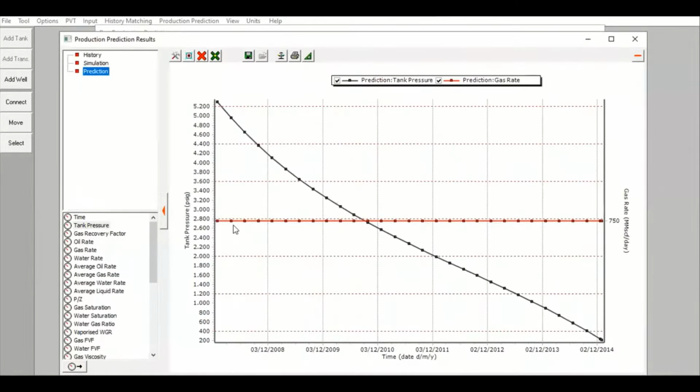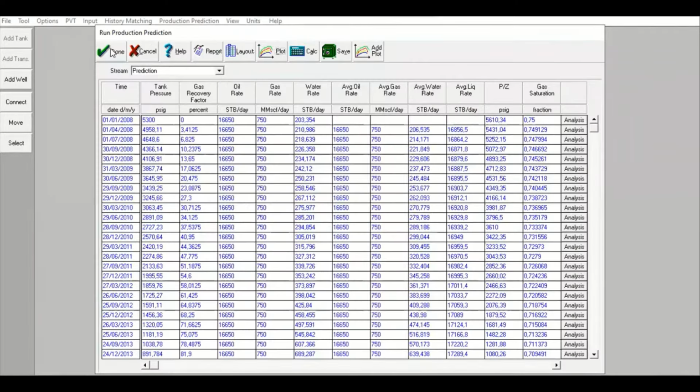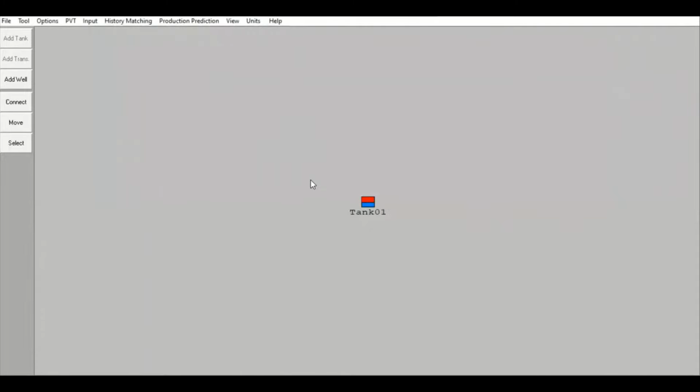All right. So this is what happens if you simulate without wells. You will get unrealistic results like this one, because in reality the reduction of the pressure is too big. Actually, we cannot produce at manifold or at surface pressure lower than 200, right? 215, if that matters. So you can do a simulation like this, but it's not realistic.